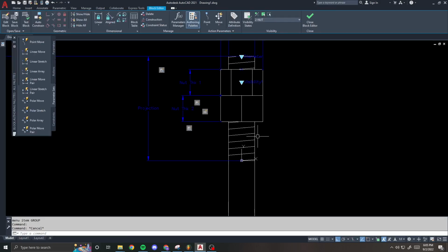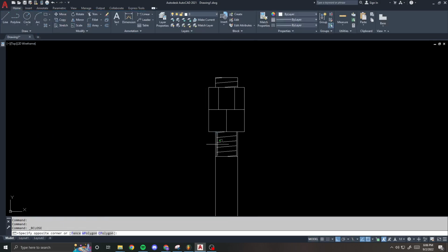Associative, yes. So if you have trouble like this, it could help to draw a rectangle. Like this. Nobody sees it, right? Do a hatch, and then apply your settings to that rectangle. Remove. There we go. Same thing here, modify. Remove, close, save.